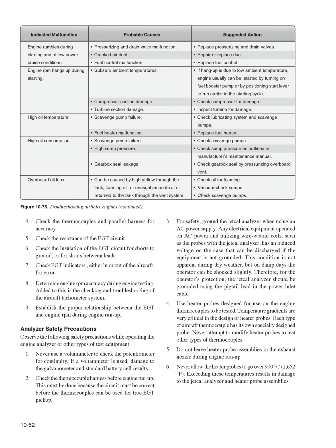4. Use heater probes designed for use on the engine thermocouples to be tested. Temperature gradients are very critical in the design of heater probes. Each type of aircraft thermocouple has its own specially designed probe. Never attempt to modify heater probes to test other types of thermocouples. 5. Do not leave heater probe assemblies in the exhaust nozzle during engine run-up. 6. Never allow the heater probes to go over 900 degrees Celsius, 1652 degrees Fahrenheit. Exceeding these temperatures results in damage to the JetCal analyzer and heater probe assemblies.